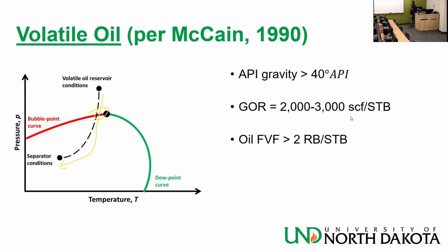By the way, trick question. Can oil formation volume factor be less than 1? The answer is no. It cannot be less than 1 because it really means that you have a reservoir that is pressurized below the atmospheric pressure. The more gas components in the liquid, the bigger the formation volume factor. Okay, because those things are going to be removed when you come to the surface. They're not going to stay there as liquid.